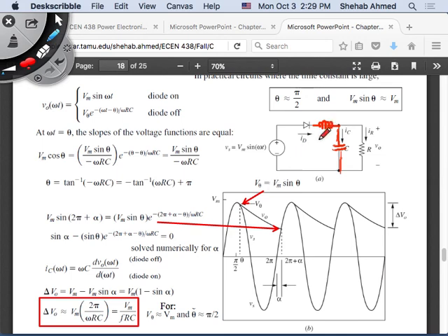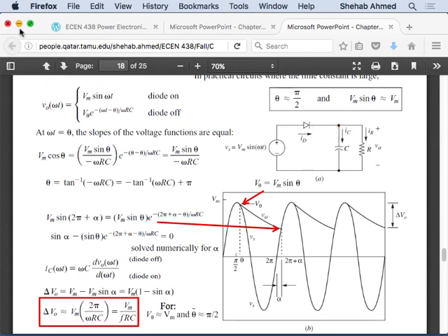So fine, you still have very similar performance, but the current will rise slowly and will fall slowly. There will be no abrupt changes in current anymore. And what will that do? That will decrease the maximum current rating of the diode. So that's good for your power electronics as well, right? So we will see that in another chapter.